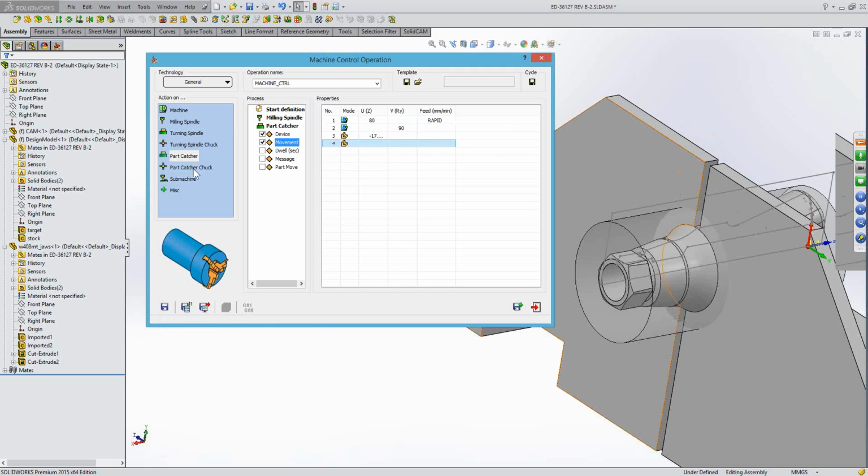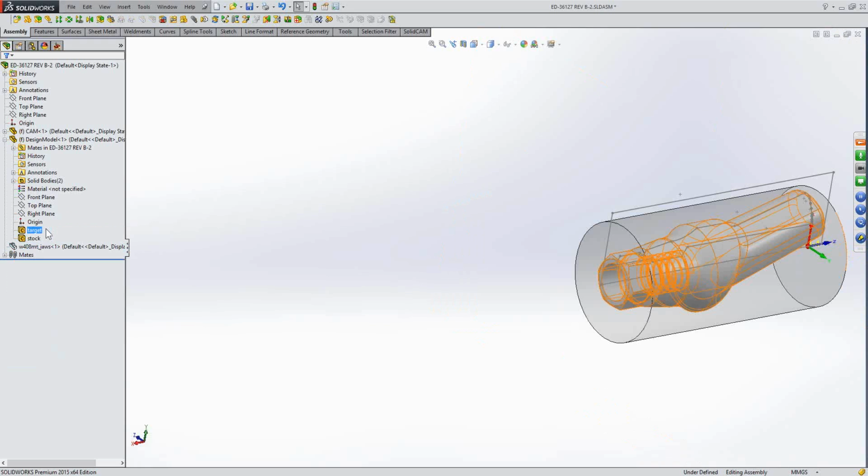Okay, so I reach the position. Here I can use jaw close, open, all this stuff. Okay, it's for the G-code. We need now for the simulation the next step, which is to use the part move. I moved the device only until now, movement. Now I move the device with the part. So using part move, go back to the limit, and you move the device to 0, back to horizontal position, and you again go to 0. Save and calculate. Hide and hide.